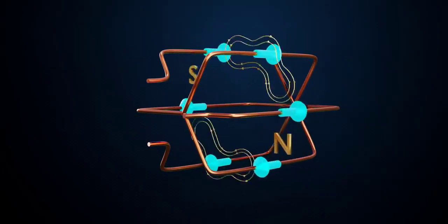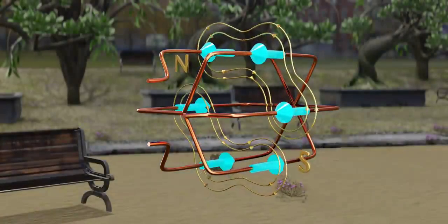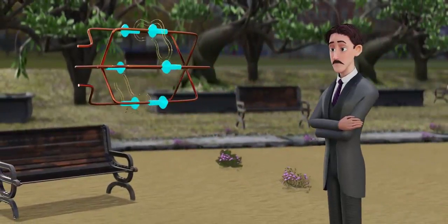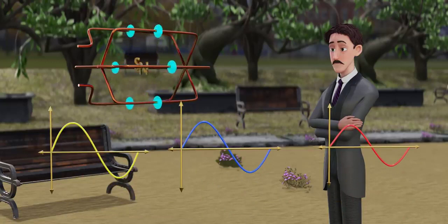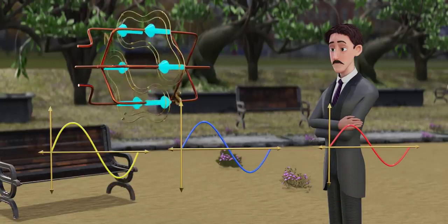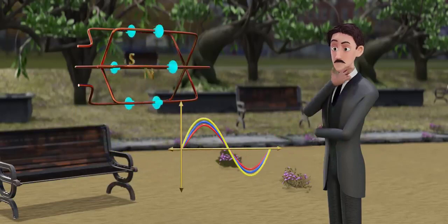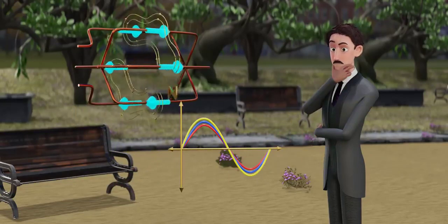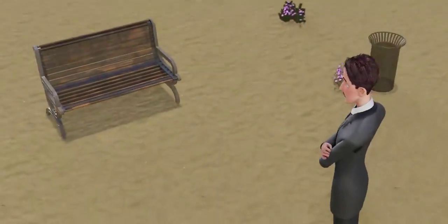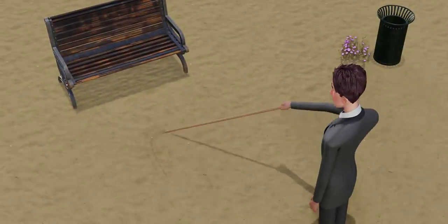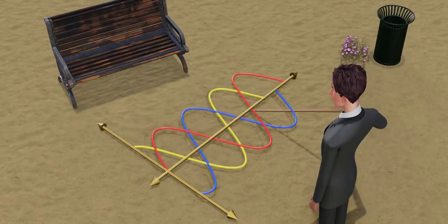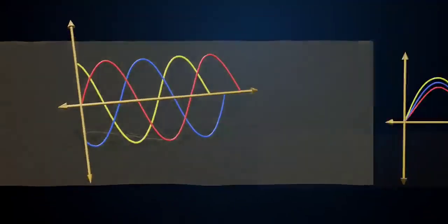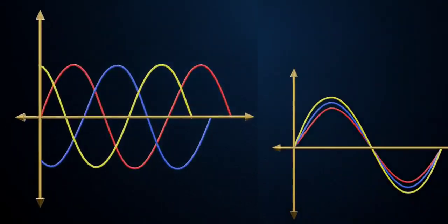This is where one of the godfathers of electrical engineering, Nikola Tesla, comes into the picture. He observed this disappointing behavior of the magnetic field's fluctuation. This field fluctuation happens because all three fields, maximum or minimum, happen at the same instant. Tesla, while walking in a park brainstorming ideas to create rotating magnetic fields, wondered what if he keeps maximum values of these three fields at different instances. Then there will be no instant when all three currents are zero or maximum at the same time. Eventually, the resultant field will not become zero at any instant. In short, he can avoid the fluctuating behavior.